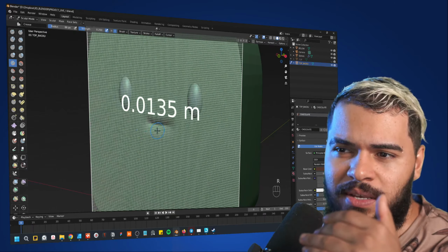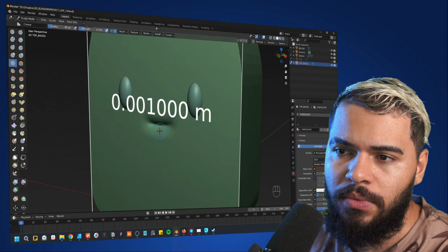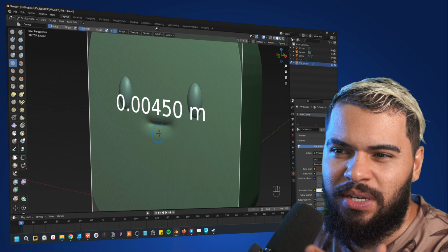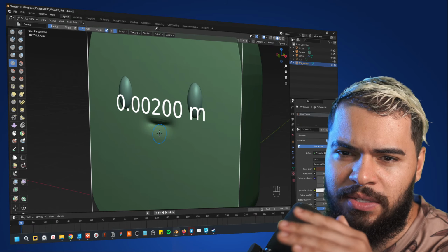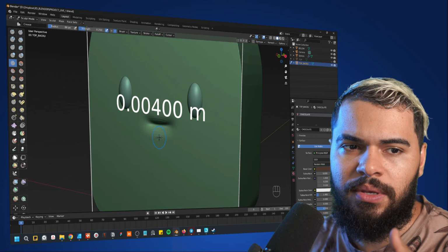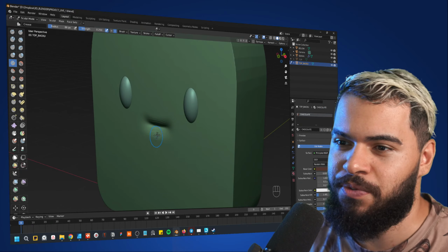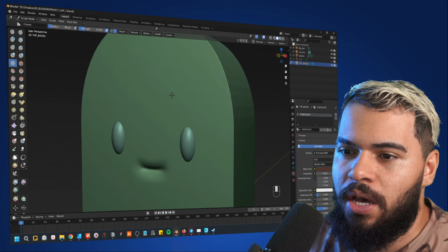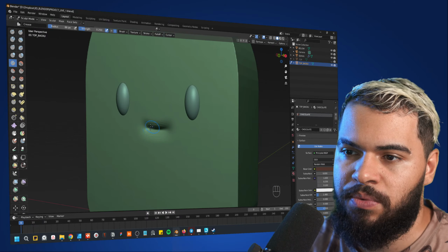don't try to use a very small density of faces and polygons, okay? Because if you do that, you can have a lot of lag. So try to work something between like this, 4, 5, 50, 2 zeros, like this. Yeah, something like in between this number. Below this, your computer can break. I mean, Blender can crash, can just freeze, or can have lags. So try to work in an affordable resolution. Make sense?